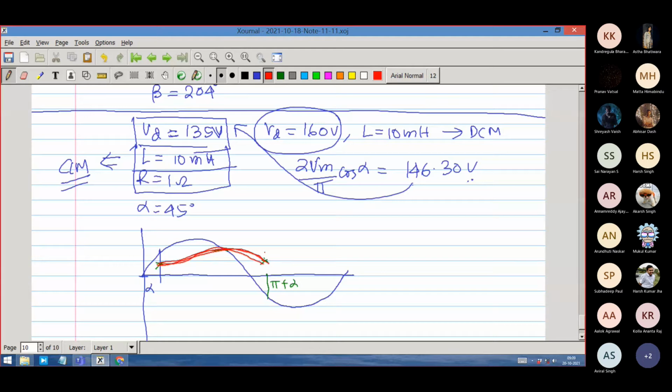The only thing that is assured is that this level of current is ID naught, the initial level of current, and then again it is periodic. That is the current waveform ID. It is in a form an imperfect current source. You remember, sometimes for simplicity to indicate that it is in CCM, whenever I put a current source on the DC side, you will understand that I mean the converter is in continuous conduction mode.